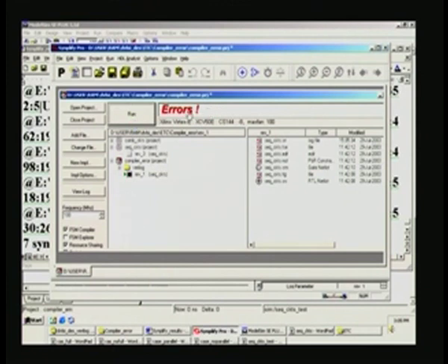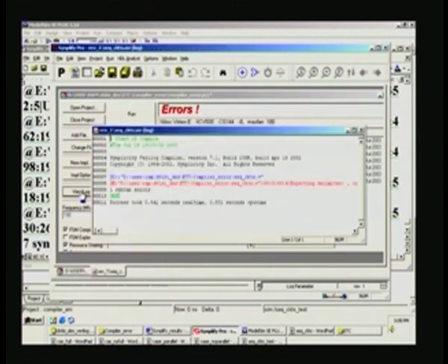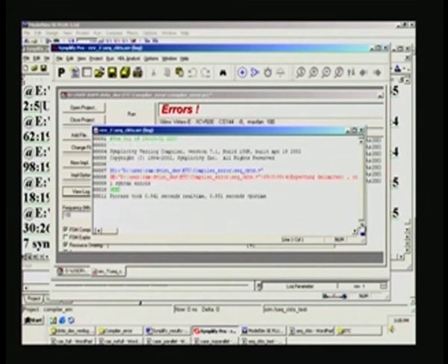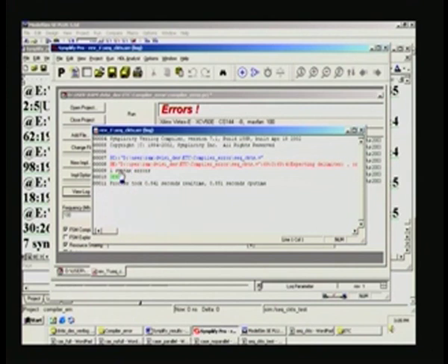It is reporting errors here, and if you view the log file, you notice that it has done nothing beyond that, because it encountered the error in the very first shot, and therefore no further report is seen within this log file, which usually is a very long file. You can see the error here, reported with an E, and what it says is expecting delimiter comma or semicolon.